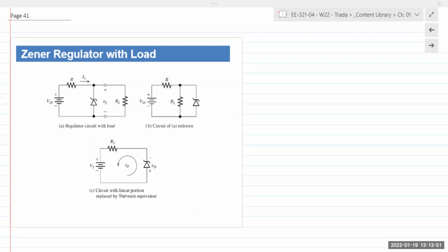Now, the resistor R that you see in series is basically a current limiting resistor. Effectively, just think about Ohm's law, V equals IR, right? If you have a load, let's say you're running a simple LED off of a 1.5 volt battery, that LED is a diode, so it does not have very high resistance. So if you just connect 1.5 volts to any LED or load, what will happen? Current's infinite, you'll just blow everything out. And so that's why you need a resistor in there.